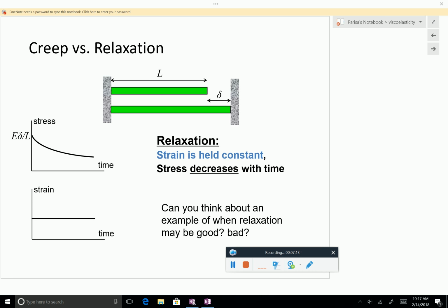I don't expect it, but have you heard about pre-stressed concrete? No? So, you are juniors. So, in pre-stressed concrete, most modern concrete is pre-stressed. You have tendons, you put them in tension, and then you pour concrete over. So this is being used to put the concrete in compression, so it can tolerate more tension. Now, if the stress decreases versus time, you lose this pre-stressing stress. So the member doesn't have the properties that you think it has.